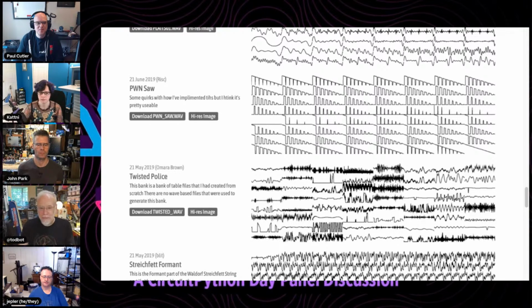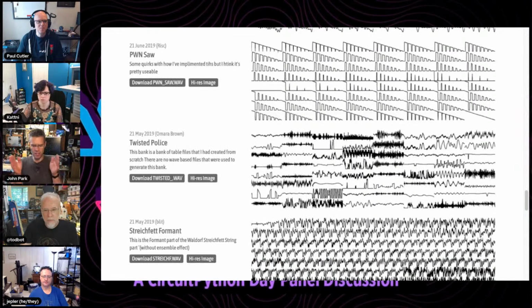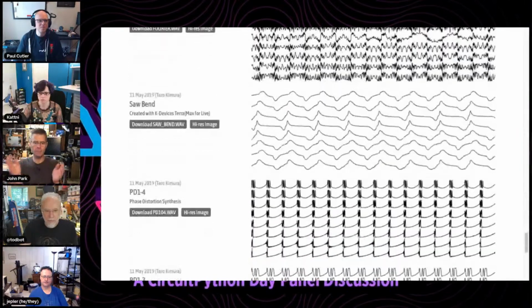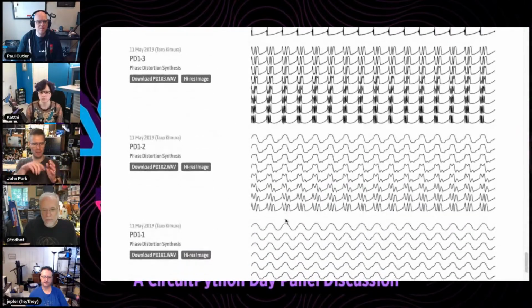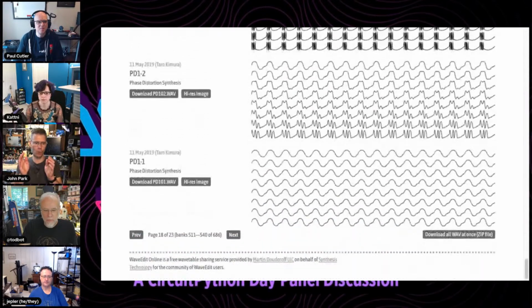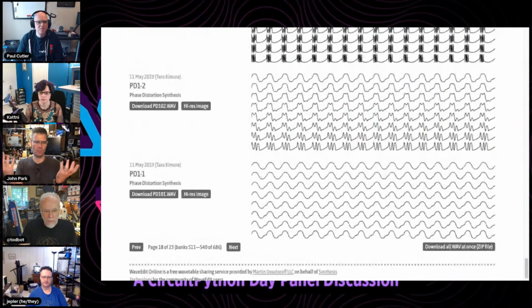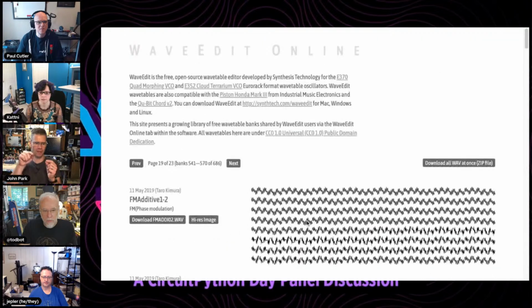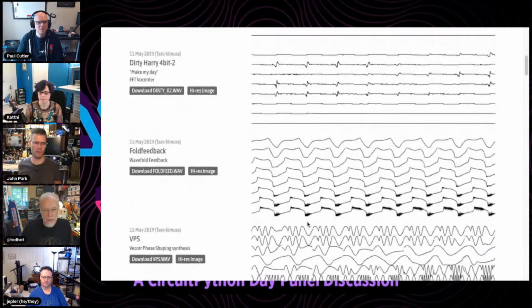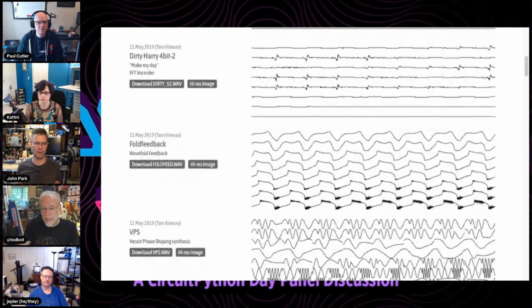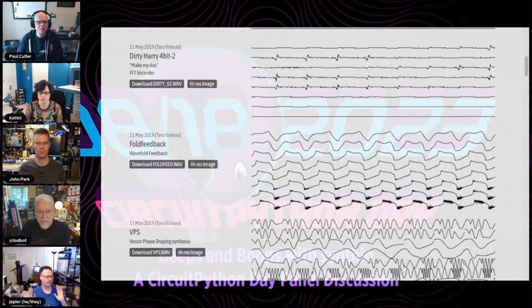And am I right that in synthio the definition of the shape of the wave you're playing can be a sine wave that's mathematically formulated, or it can be essentially a lookup table, which is what these end up being, right? A lookup table of wave points over time. Actually, Jepler could probably speak to this better than I can. It's always just a buffer of memory. There's some modest cap of how many elements it can be. I think maybe it's 1024.